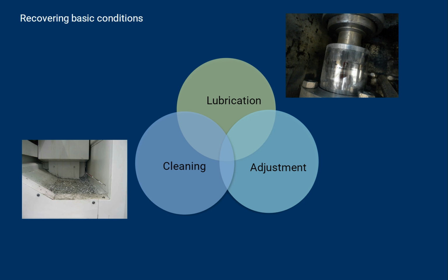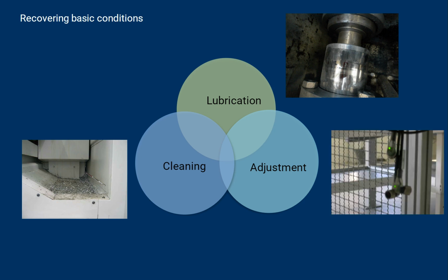If components or parts are not properly tightened, vibrations, misalignments, safety risks, leaks, and loss of precision in machinery can occur. These defects can quickly escalate from moderate to critical, and result in effective production time losses, as frequent adjustments are required. Restoring the three basic conditions of the equipment is the most important technical purpose of the initial steps of autonomous maintenance.